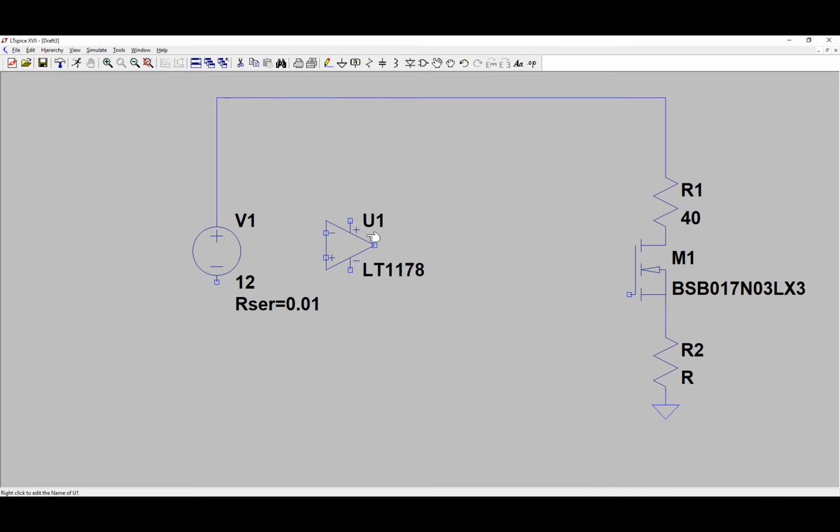So till now we just connected the LED and the MOSFET that is giving the current to the LED, and we have a feedback resistor. I will take a feedback resistor of 0.5 ohm. Now I found the LED of 9 volt and 400 milliamps.